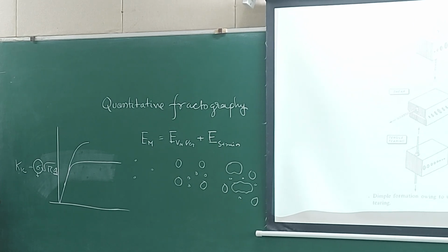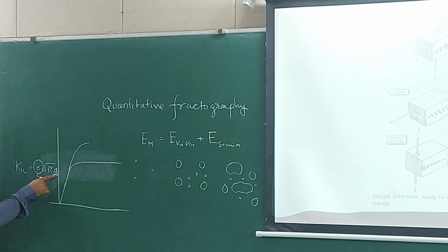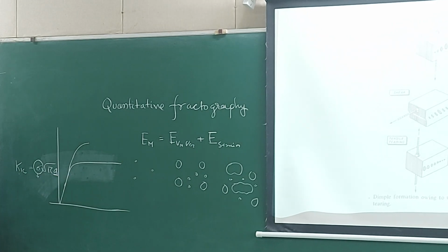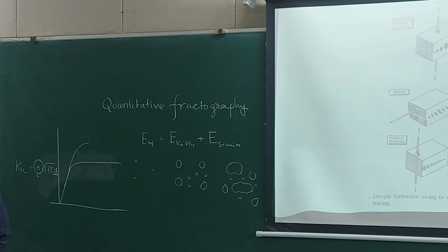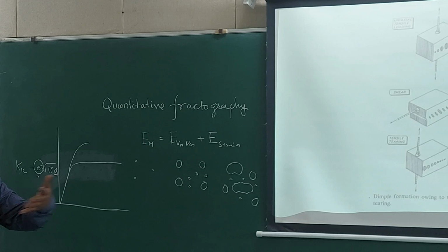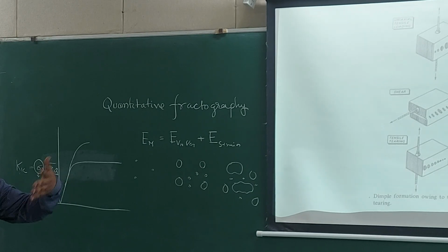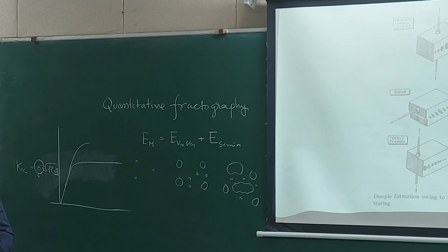For the lower one, K1C is larger, so A will be larger. So you will need a very high, very large crack so that fracture can happen. That means the void has to increase to a very large diameter so that it can achieve that critical crack.